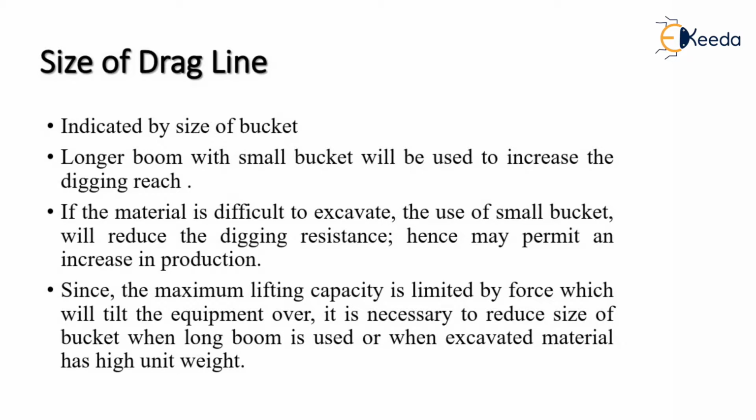Now the size of the dragline. The size of the dragline is indicated by the size of the bucket. A longer boom with a small bucket is always used to increase the digging reach. Now, if the material is difficult to excavate, the use of a small bucket will reduce the digging resistance.